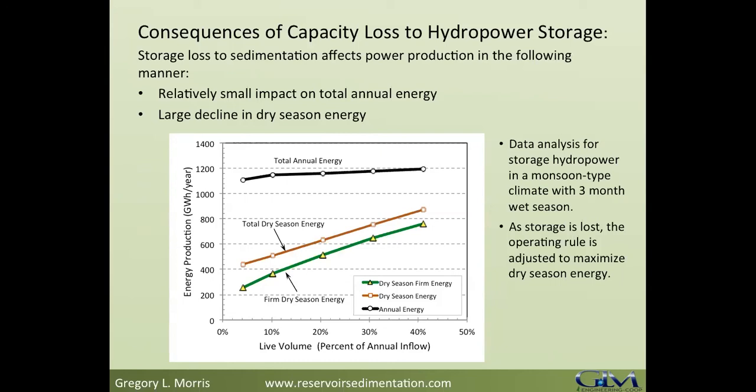In the US, we don't have enough sediment gauge data, and we also do not have enough monitoring data of the sediment process in reservoirs. The minimum that you need really depends on what type of strategy you're going to use. If you're going to be dredging, you probably don't need an upstream gauge. If you're going to be doing something like sediment sluicing, it's going to require quite a bit of data to design that process properly. Yeah, this might be a good question to talk about a little bit in the monitoring talk. I'll write that one down.